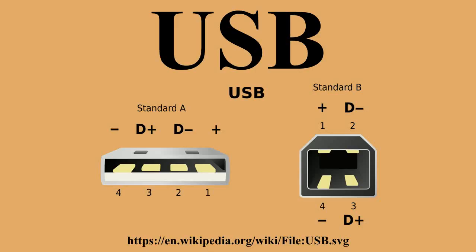System design. The design architecture of USB is asymmetrical in its topology, consisting of a host, a multitude of downstream USB ports, and multiple peripheral devices connected in a tiered star topology. Additional USB hubs may be included in the tiers, allowing branching into a tree structure with up to 5 tier levels. A USB host may implement multiple host controllers, and each host controller may provide 1 or more USB ports. Up to 127 devices, including hub devices if present, may be connected to a single host controller.